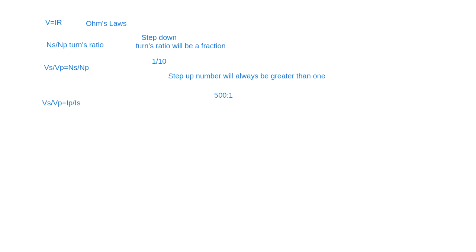But just recognize that our worst equipment that we ever had was single phase half wave equipment. And when we had single phase half wave, that used the highest techniques and the longest exposure times, because they couldn't flip that negative side of the pulse up to the positive.